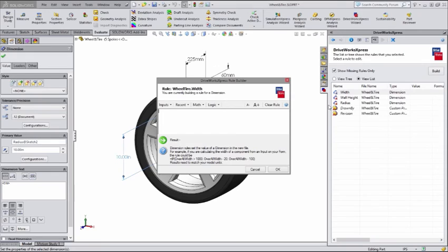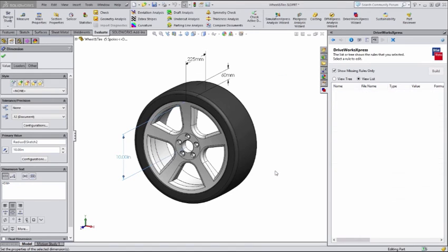Next, we're going to do the wheel width. If this was just an inch input, I could simply select the wheel width input right here, and that'd be it, and it'd equal 200. But since we need to do a conversion over to inches from millimeters, I'm just going to divide this by 25.4, giving us the inches. Simple as that. I'll go ahead and click OK to create that.